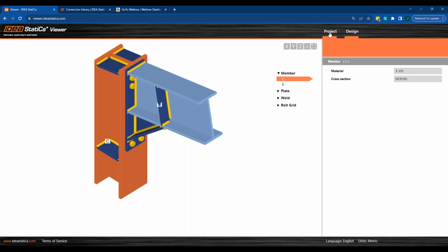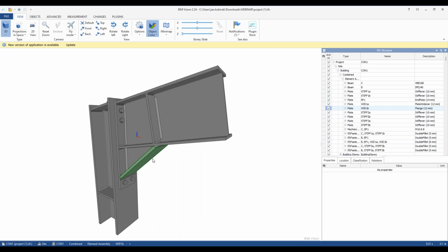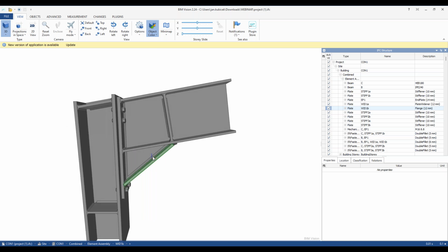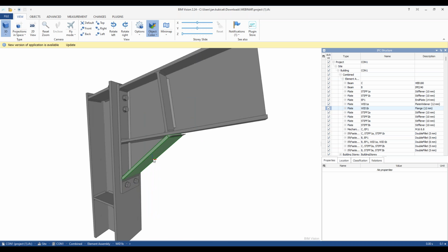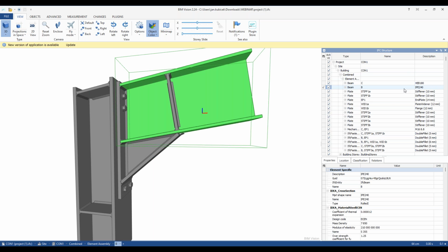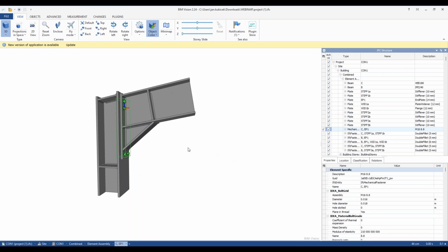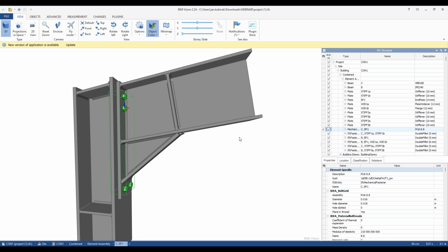That's not new, but what's new is this IFC file export. So similarly to Connection app, you can download the IFC, and if you use any IFC viewer, there is a whole range of them, free of charge typically, you would find something like this. So quite a lot of parameters related to every element in the scene. So you can see again the cross sections, the materials, design codes. You can see information about bolts as well, welds. So now you can use it for additional work.